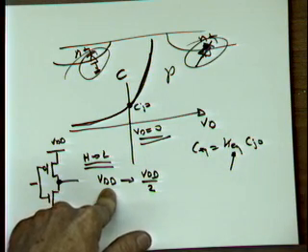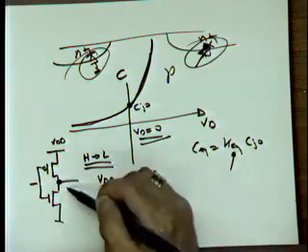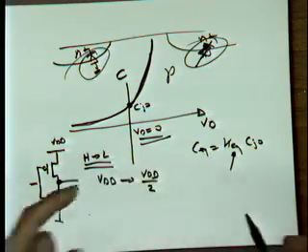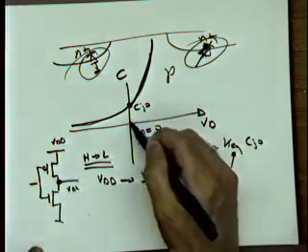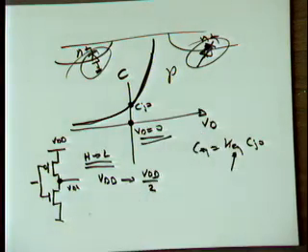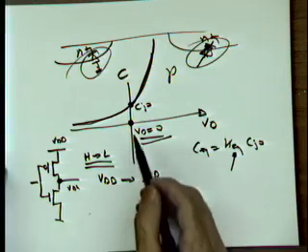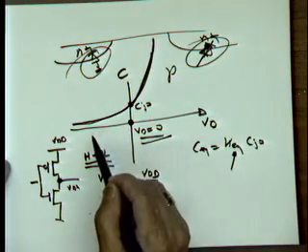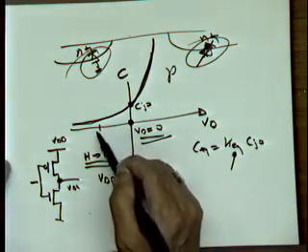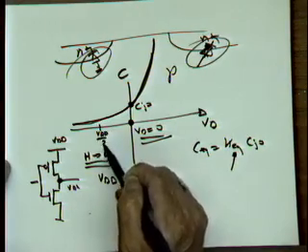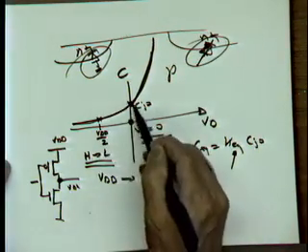0, right? The voltage is VDD, this is at VDD, the well is at VDD. So we're basically in this point here. And then this is going to start to discharge. We see that the diode is going to get more and more reverse biased, so it's going to go to VDD over 2. So these are the extreme points.